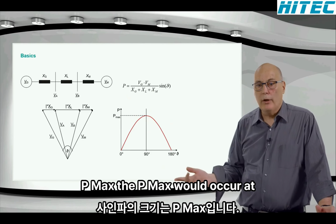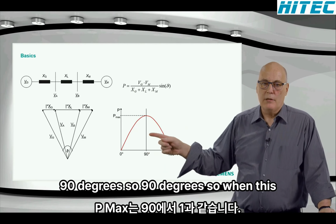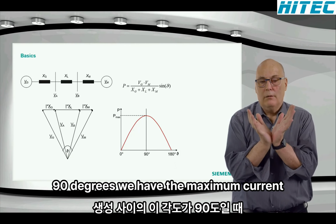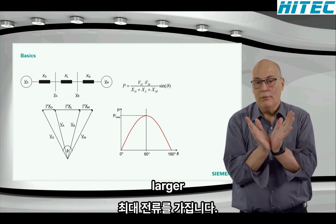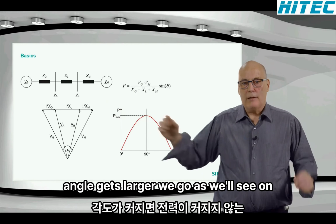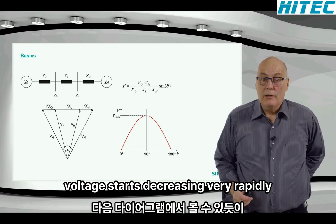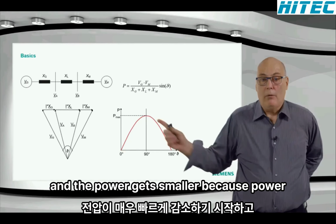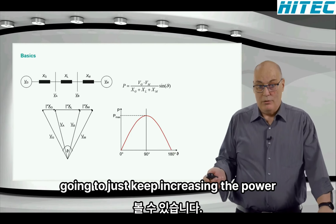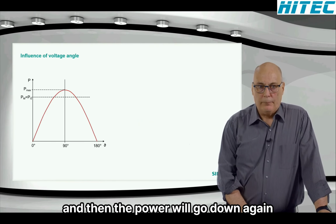The P max occurs when the sine is equal to 1, at 90 degrees. So when the angle between the source and generation is 90 degrees, we have the maximum power. At that point the current could get larger, but the power does not get larger. Why does the power not get larger? If the angle gets larger, as we'll see on the next diagram, we go into an area where the voltage starts decreasing very rapidly and then the power gets smaller, because power is current times voltage. So simply increasing the current is not going to keep increasing the power. At some point the voltage is going down and then the power will go down again.